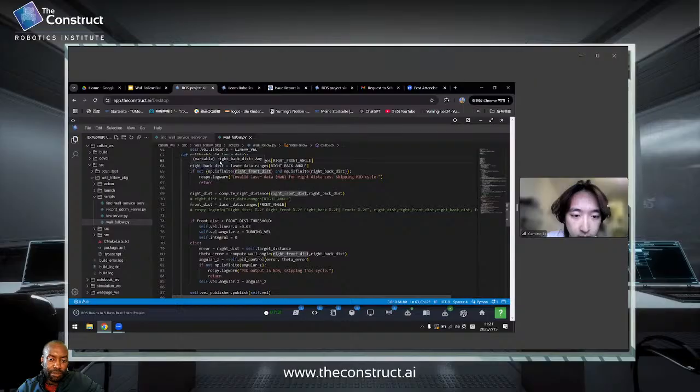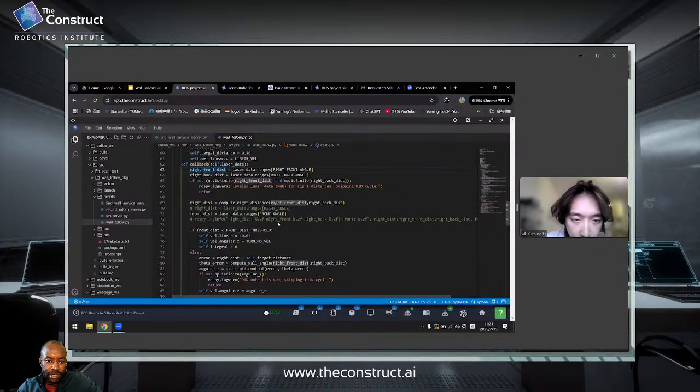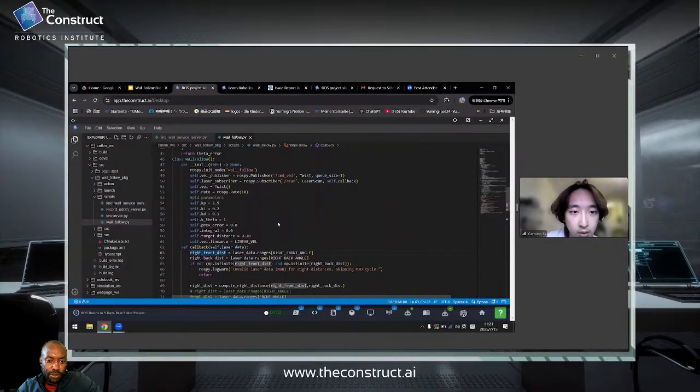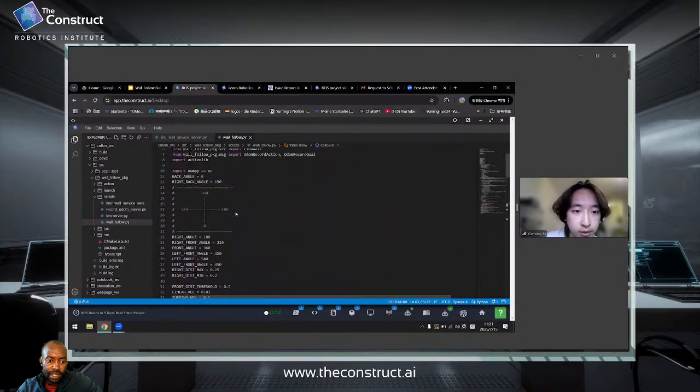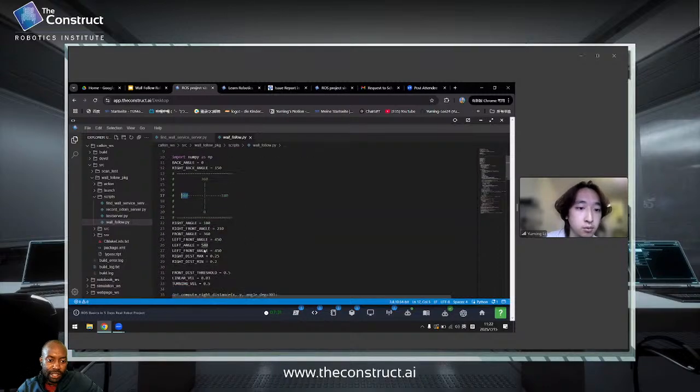That is a laser scan index that checks how far the wall is. On what index is it in your laser scan ranges data? Originally it's 180. So that would change to what value? To this 540.